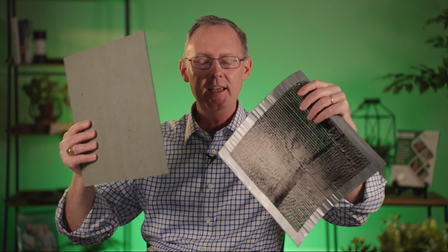And this is some carbon fabric, actually that came from my PhD. And you can see it's stitched. There are carbon fibers in this particular fabric that run this way, and it's stitched together. So that's an example of a carbon. If you see black fibers, that typically means carbon. I've got some other fabrics here. This is actually an e-glass, and it's got a chopped strand on this side. And what happens is you basically saturate these with a resin. So the funny thing is the difference between this and this is literally just adhesive. I mean, I guess if you're a redneck, you say it's just glue.